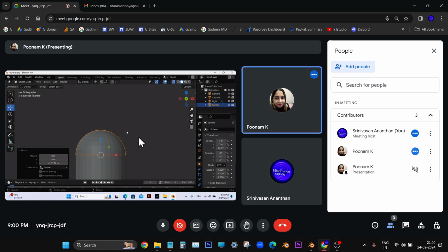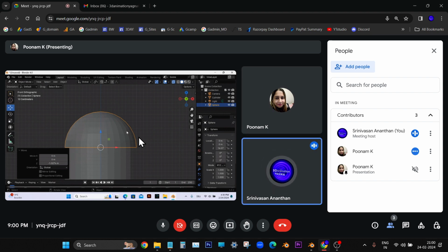Function dot. Yeah, okay. Now, one thing we have to do: the object is in gray color, no? We are not able to see it clearly. We can do one thing. On the top right side we are seeing many render modes. After the X-ray mode we are seeing one icon, and the shade mode is on, that is, solid mode is on.